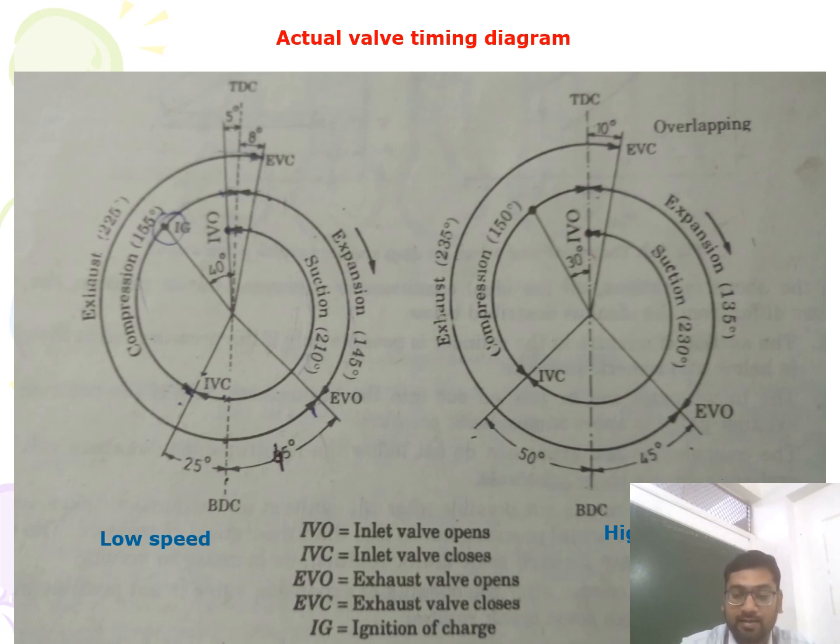By closing the exhaust valve a few degrees after TDC, the inertia of the exhaust gas tends to scavenge the cylinder by carrying out a greater mass of gas left in the clearance volume. This increases the volumetric efficiency, and if the volumetric efficiency is increased, more charge gets inside the cylinder, more burning happens and more efficiency will be delivered by this engine.